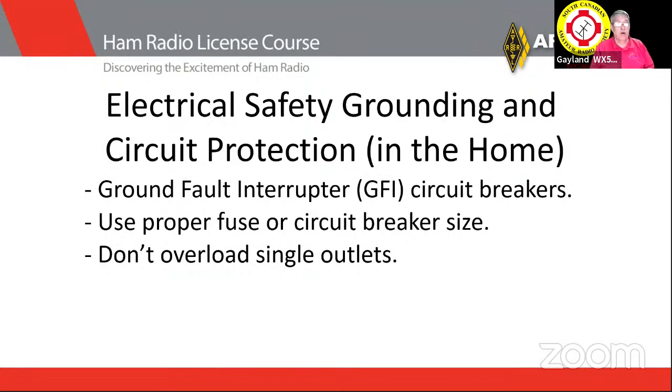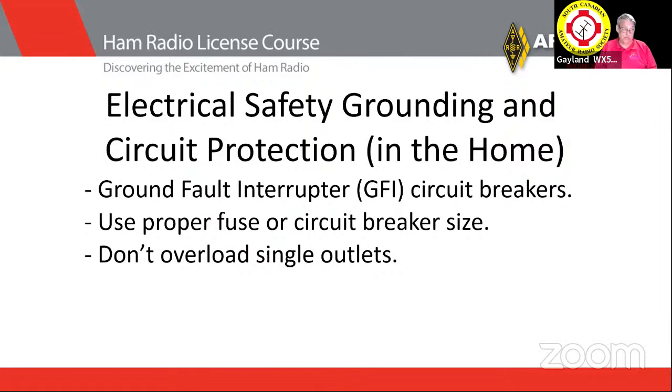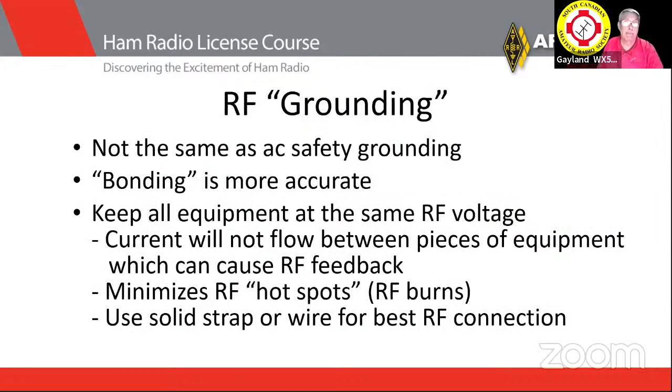Use GFCIs, proper fuse sizes, use fuses, make sure all your equipment is fused, and don't overload your outlets or your power strips. Remember that grounding in the RF world is not necessarily the same as your electric system grounding. You want to bond your stuff. Keep all of your equipment at the same RF voltage, so current won't flow between pieces of equipment. Minimize your hot spots. Use solid strap, not braided, or wire for your best RF connection.